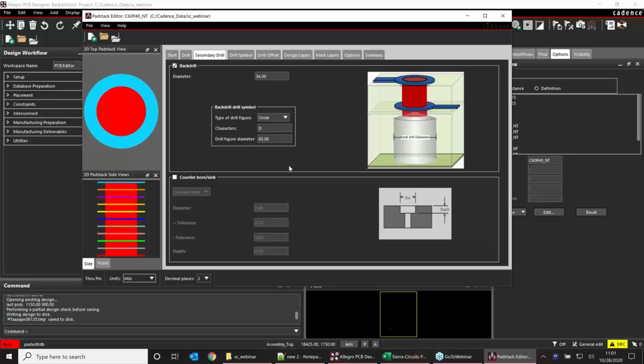How does one decide thickness of pre-preg? Thickness of pre-preg is generally decided by the total number of layers. Basically, a generalized version of the question is, how do you decide the dielectric thicknesses between various conducting layers in a PCB?